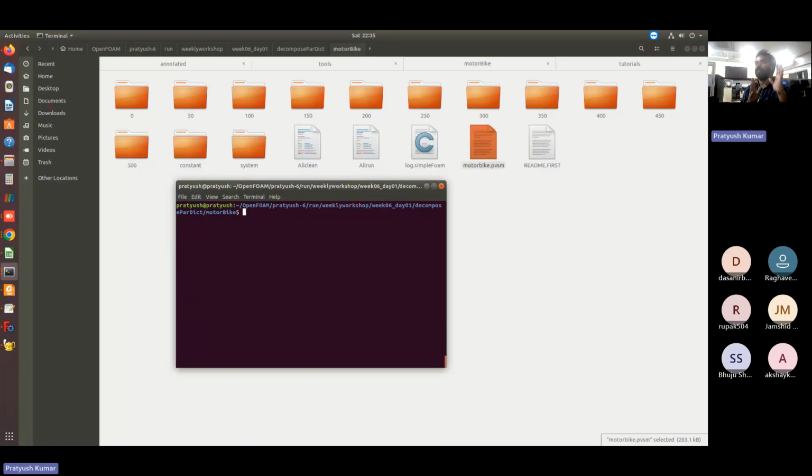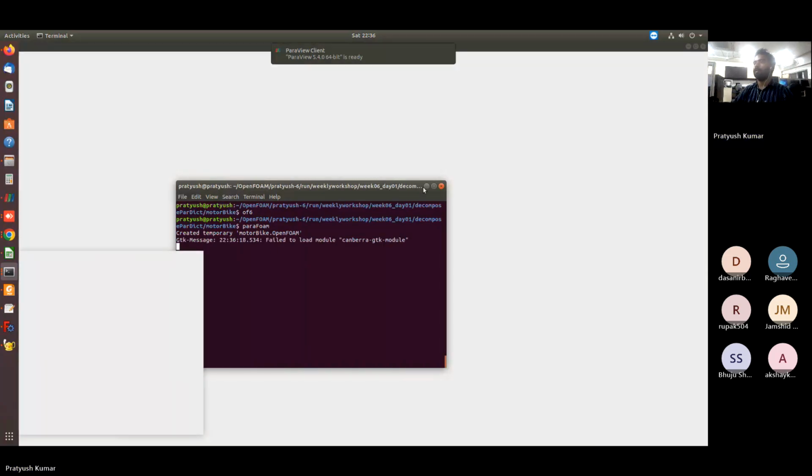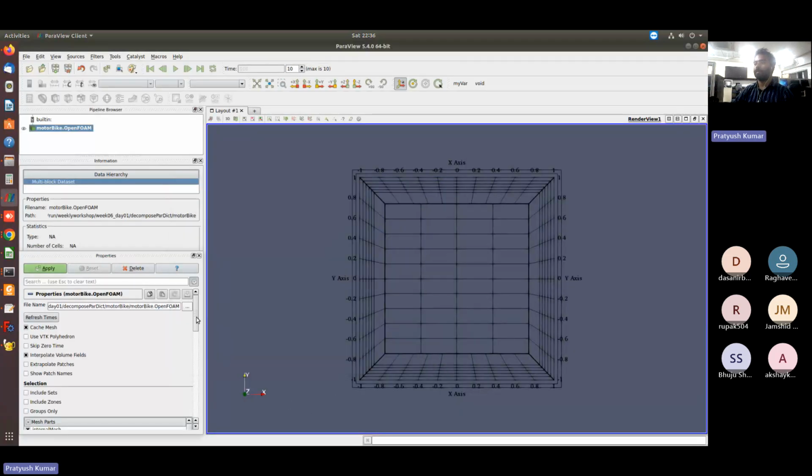So we are performing a parametric study, and we want to save that image that we get at the final simulation, the final result. That kind of task we want to perform for m number of test cases. So for that purpose we can just open this test case using this ParaFOAM command.